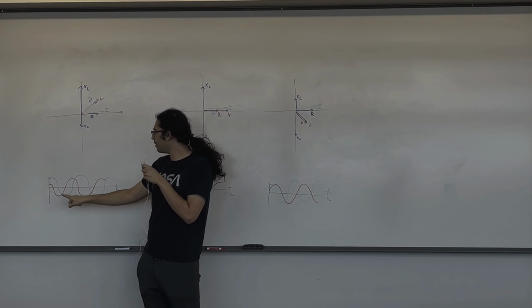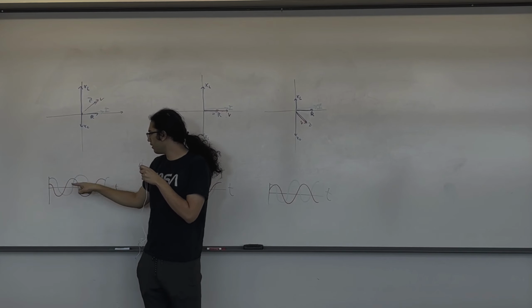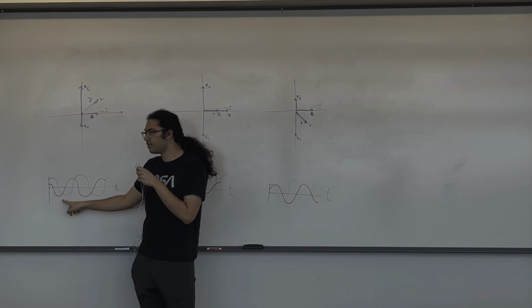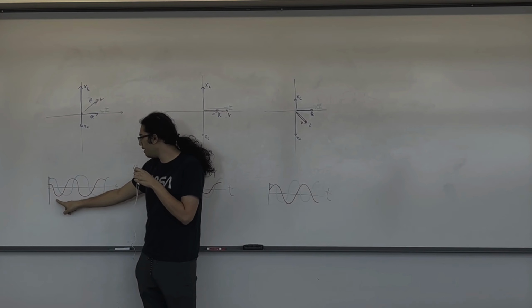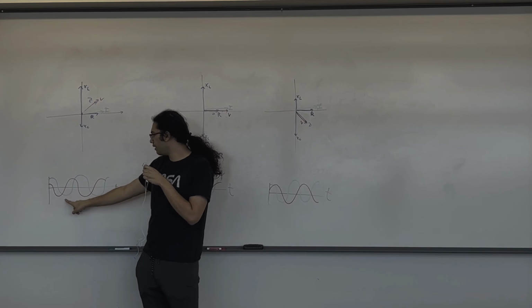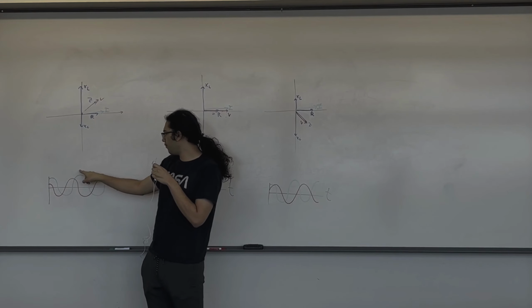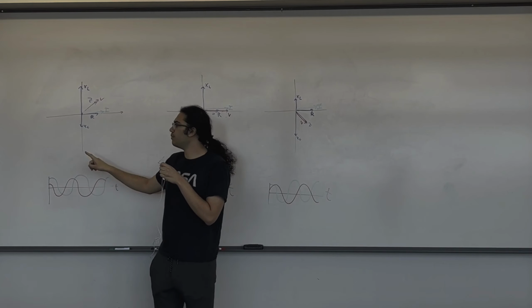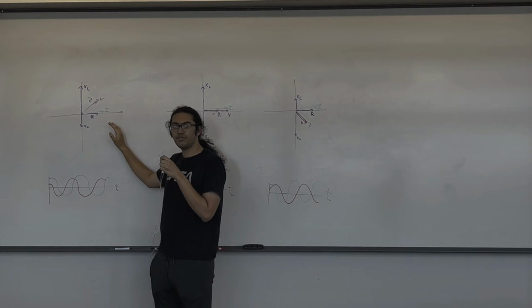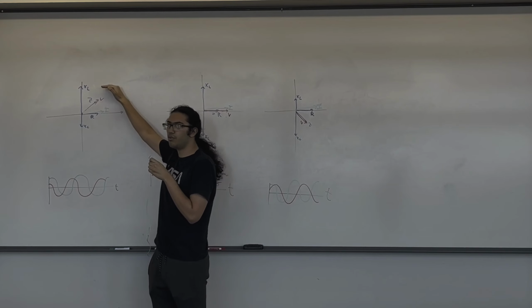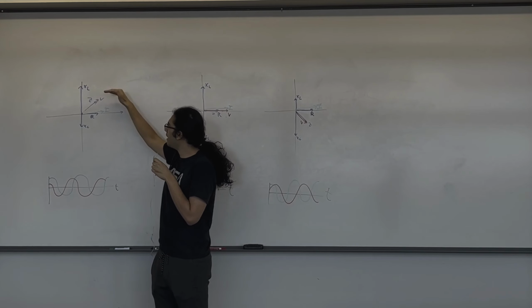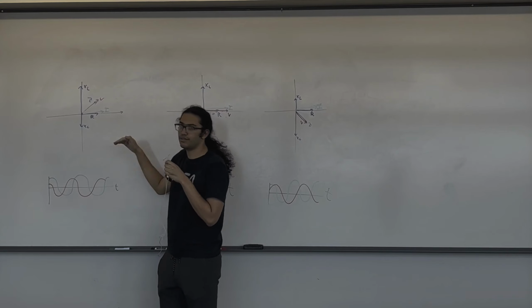And we can see that the voltage is going to be leading the current, which means that as we look at our graph, we're going to hit our peak voltage before our peak current. So in this case, we say that this is an inductive circuit because there is more inductive reactance, which means that our voltage is leading our current.